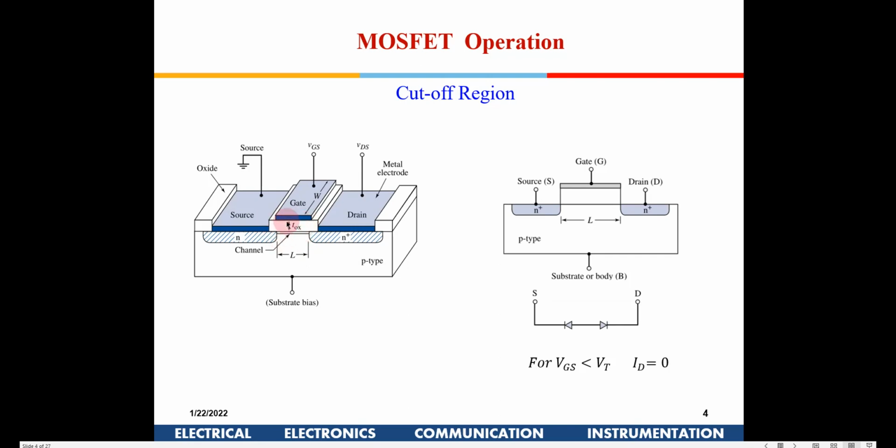TOX is the thickness of the oxide. It is silicon dioxide. Initially silicon dioxide was used, now HfO2 is used, and over that you have a conduction layer, which is known as the gate. The gate was initially made of polysilicon, and now we have aluminum, molybdenum, and other metals coming in as the gate.